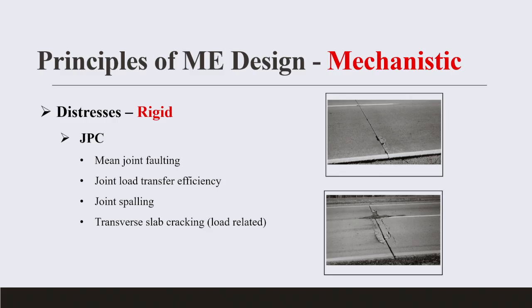I don't know whether the factors that affect alligator cracks in Nigeria are maybe traffic, this, but this is the impact. So there are a lot of those equations there, and someone can work on those transfer functions or equations, and come out with key distresses and put them in the software. That's when you are doing the calibration of the software for your country.